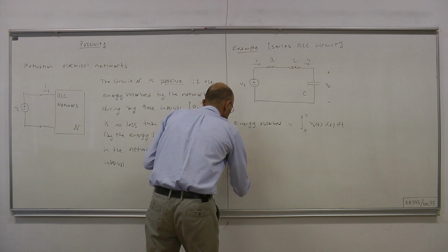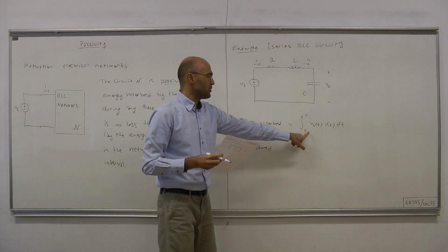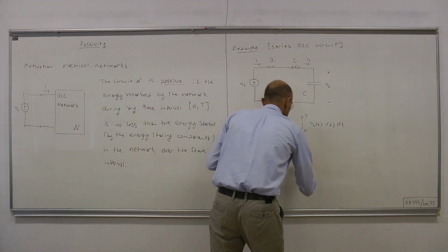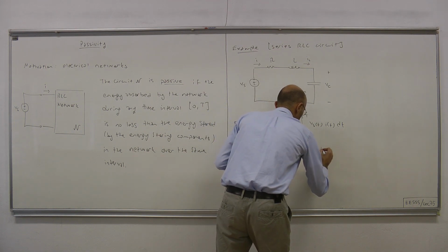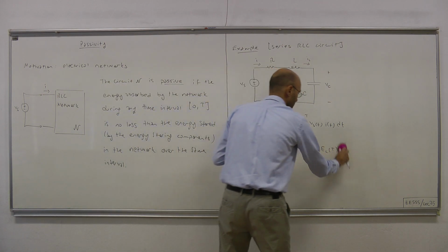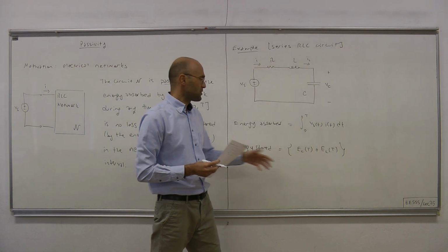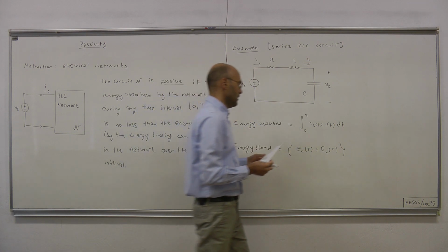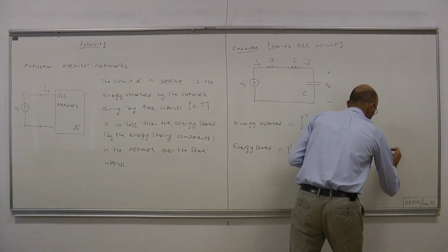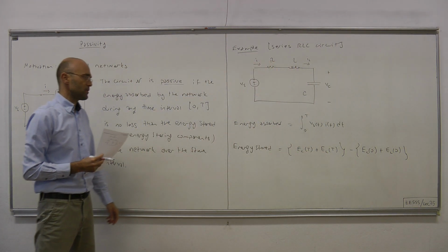As for the energy stored during the interval from 0 to capital T, it is the total stored energy at time T by the energy storing components, namely the capacitor and the inductor, minus the initial energy, which has to do with the initial conditions of our dynamic components.